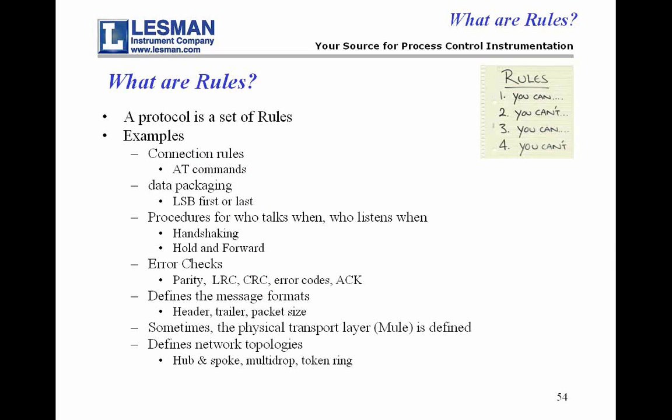That's actually a protocol. AT commands are part of a protocol. Data packaging refers to things like the least significant bit or the least significant byte. Does that go first or does it go last? That's very important because bytes are nothing but ones and zeros, and you've got to get them in the right order in order to interpret them correctly at either end.